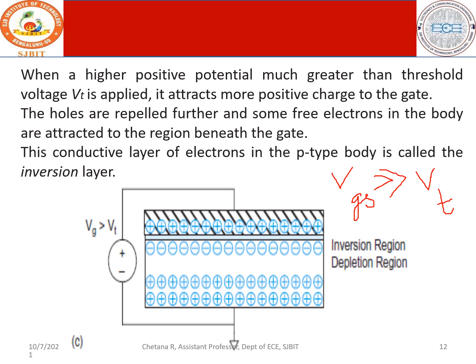Please remember one more point I forgot to tell in the initial case. Your substrate is rich in positive ions. That doesn't mean there are no negative charge carriers. A few negative charge carriers are also present, but the majority will be positive. Whatever leftover negative charge carriers are present in the substrate get attracted to the positive voltage at the gate, and that too when it is a bigger voltage.